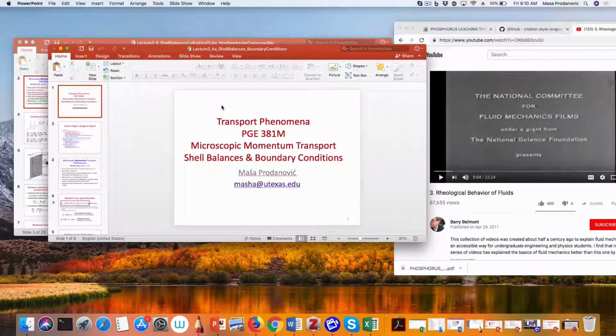In one case, when we were solving for shear stress, we got a general form of shear stress, tau RZ, that has a dependence. There's that one term which is something times R, and then plus something times 1 over R. Okay? And that is mathematically correct. Math doesn't know whether R is 0 in our geometry or not.